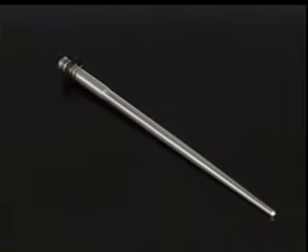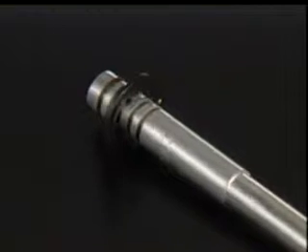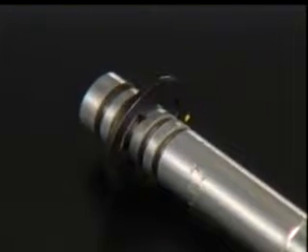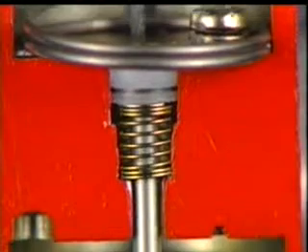At the tip of the needle there are 5 grooves. When the clip is lowered, the jet needle is pulled upwards, so that the amount of fuel dispensed from the jet needle is increased. And this produces a richer fuel-air mixture.